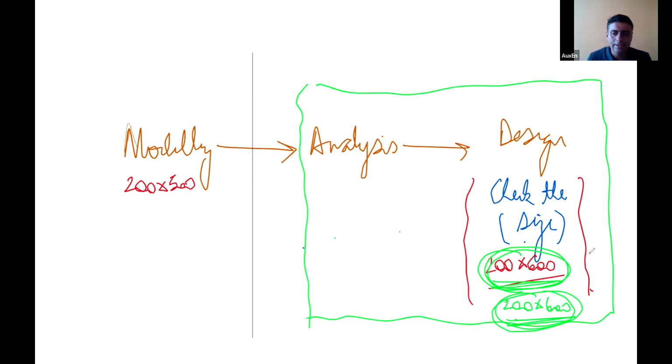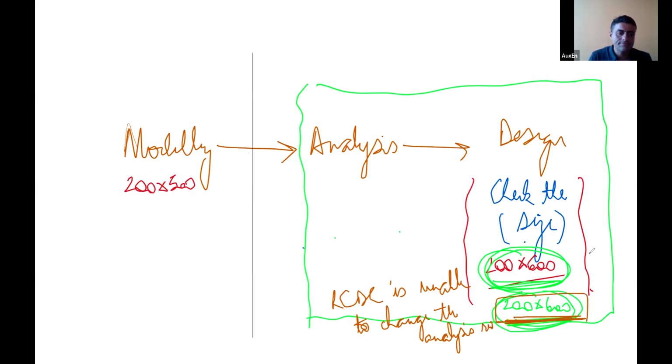So when I change the size, RCDC is unable to change the analysis results. Even if you are changing the sizes, the new sizes will be checked for the old analysis forces.